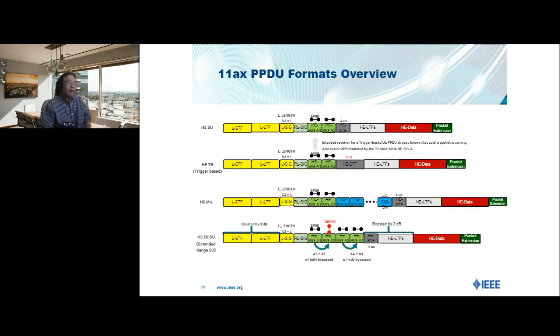Before we dive into details, I want to give the overall feeling about what this PPDU looks like. Okay, so here I give you the HE SU, HE trigger-based, HE MU, HE ERSU PPDU. This slide is great, it provides an overview of all the different parts of the different PPDU formats.